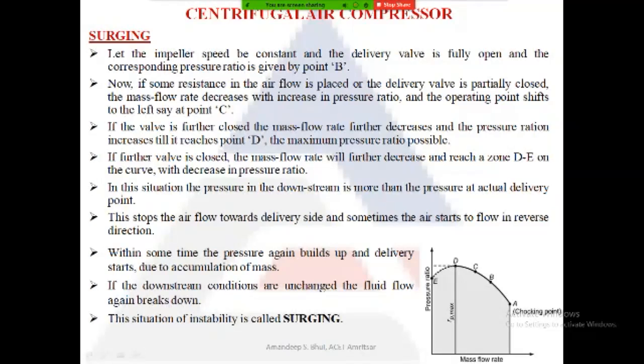Now this situation of instability, where sometimes the air is getting delivered, sometimes backflow of air is taking place, again for some time the air is getting delivered, again the backflow of air is taking place. So this instability of the compressor, this situation, is known as surging.